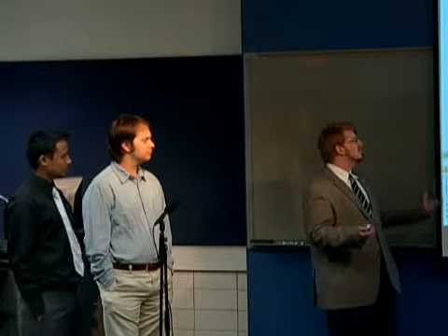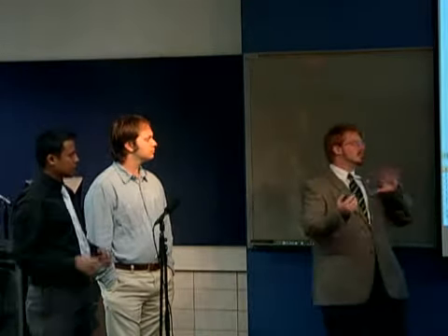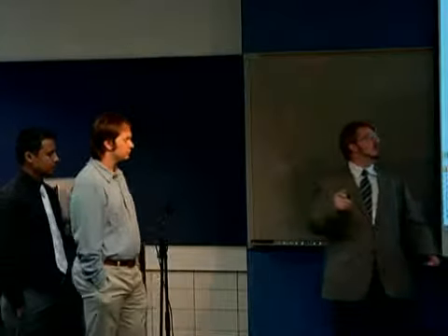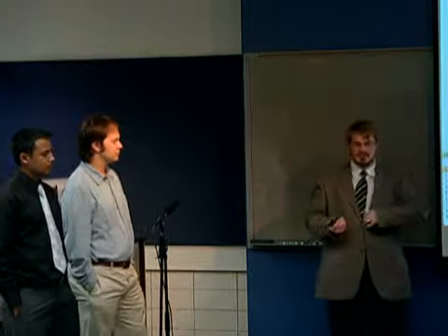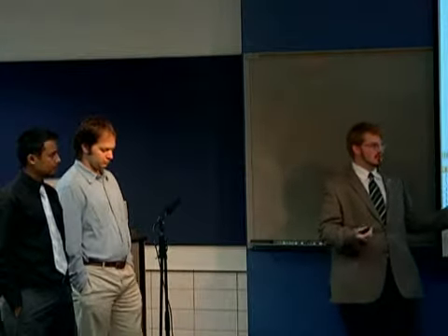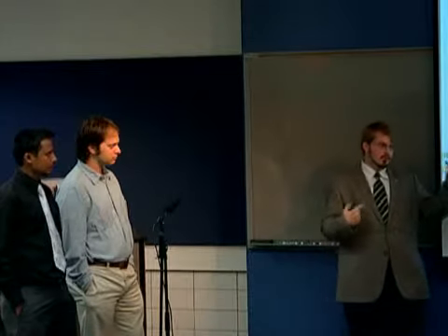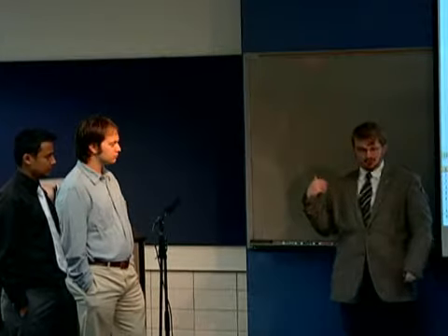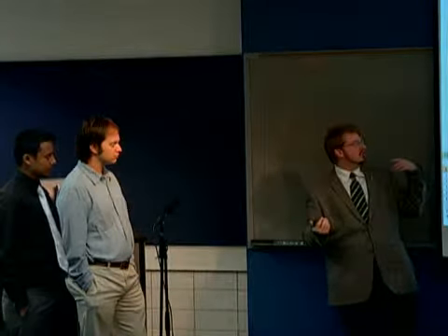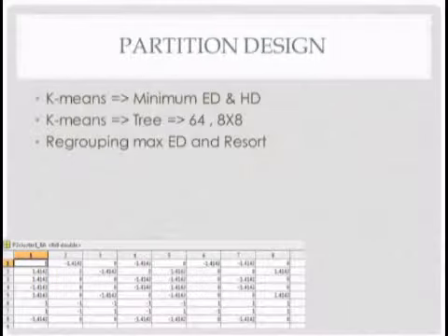So what I did with how to design my partition, knowing that those effects are going to happen: generally, for a lower signal to noise ratio, the white Gaussian noise is going to play more of an effect. But for higher signal to noise ratio, and depending on the environment, you're going to have Rayleigh effects. If you're sending something from a ground station to orbit, you're going to have more white Gaussian noise. But in a city, like New Orleans here, you might be more inclined to have Rayleigh fading because of the buildings and how they interfere.